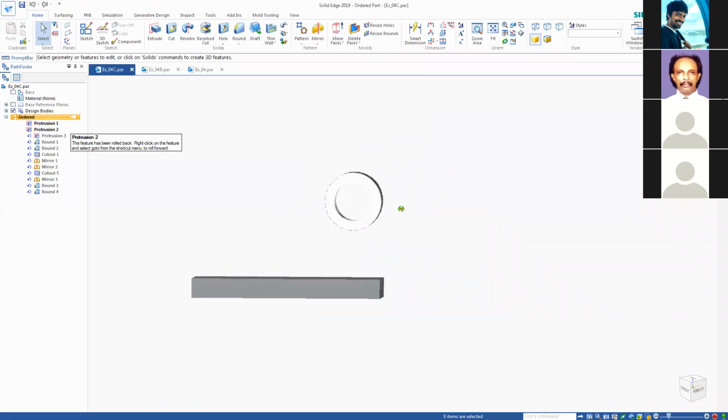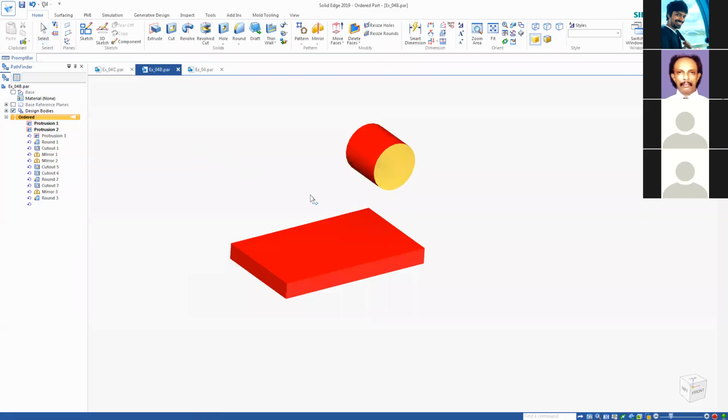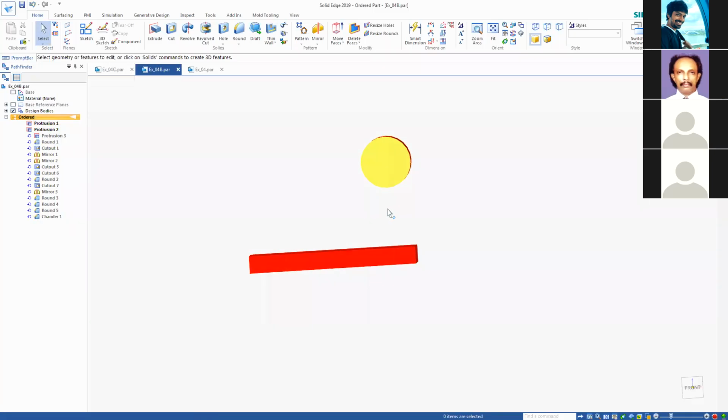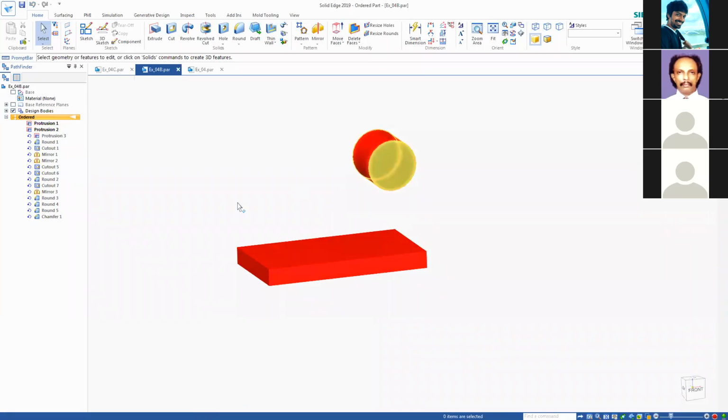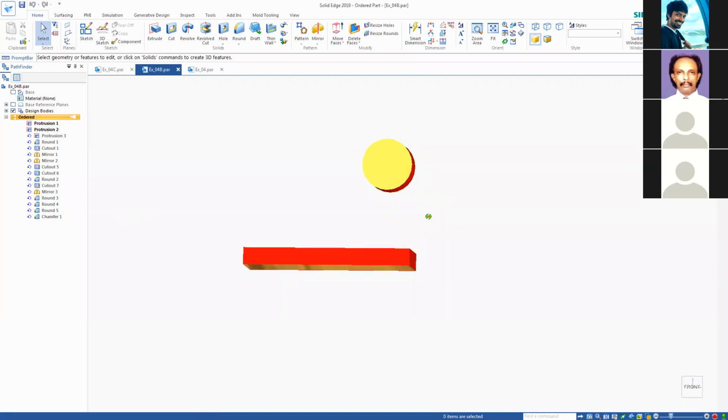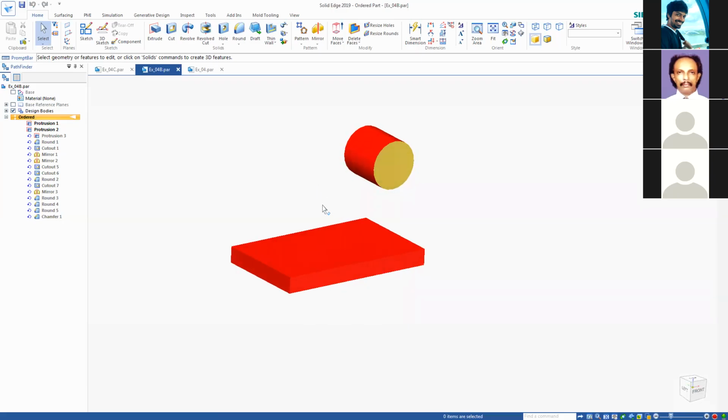And what you should maintain is you can see this edge is always vertical. And that edge is also vertical. You can try by changing the dimensions, for example. I don't want to do this one right now. You can try, but make sure you maintain your design intentions. As you model, as you add more features, from time to time, you can verify your model behaves according to your intentions. So if you try to do these things at the end, it will be too late.